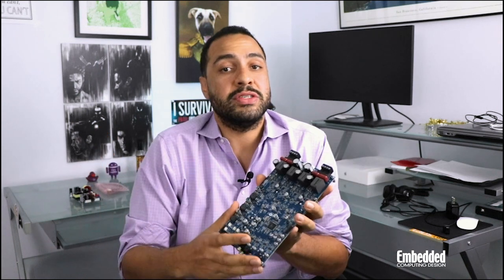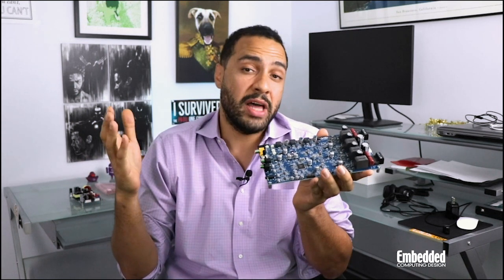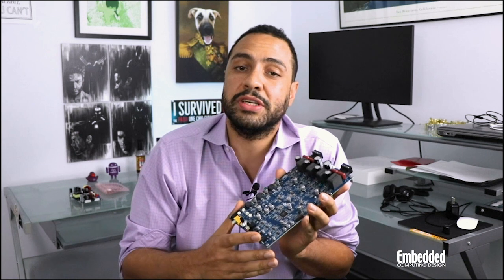Because the eHEMT transistors provide a higher electron velocity than silicon or silicon carbide alternatives, this allows the GaN Systems transistors to produce unprecedented switching efficiencies of more than 96% at full load, at least in the reference design. The technology also contributes to reduced component count and a smaller overall size of the power subsystem in high-frequency switching devices like audio amps.